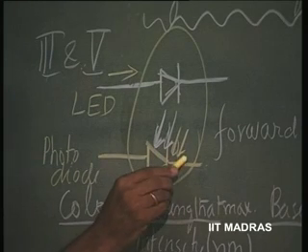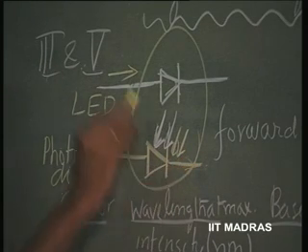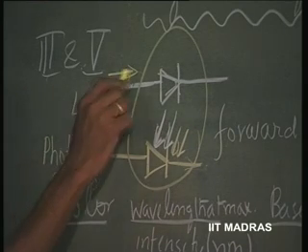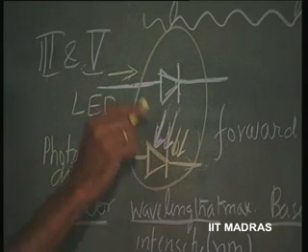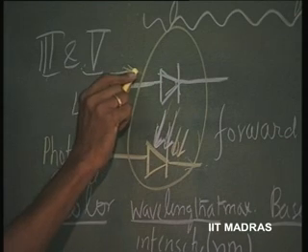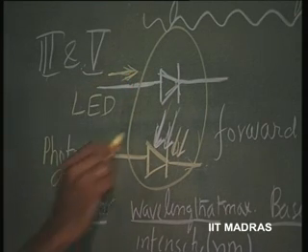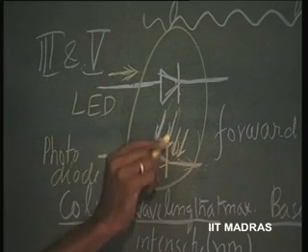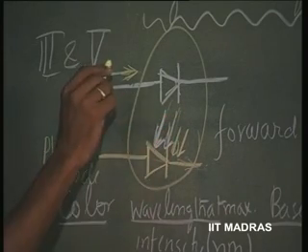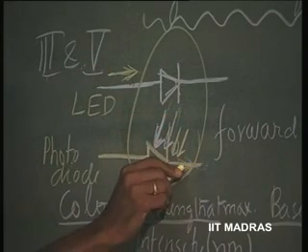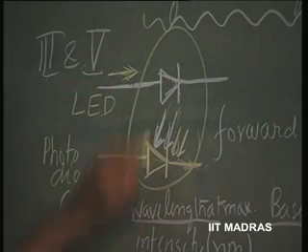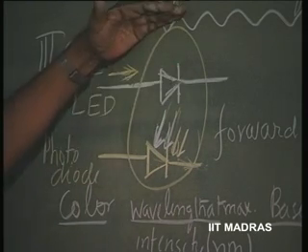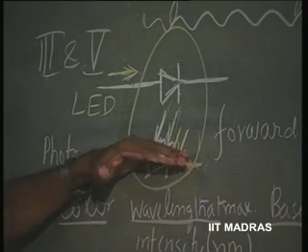So, this current which is generated here is dependent upon this current. This light intensity is dependent upon this current, and the current generated here depends upon the luminance level of this here. So, in turn we have generated a current dependent upon this current, and these two are perfectly isolated. So, this can be in one circuit and this can be in another circuit.